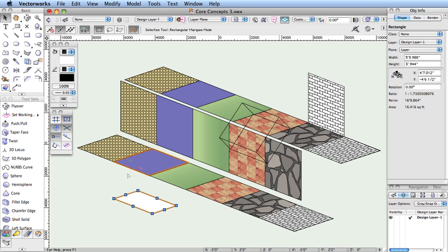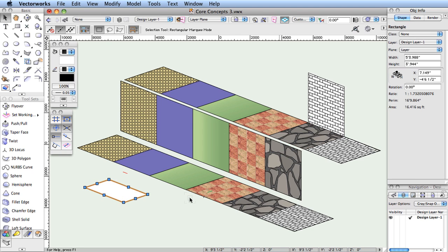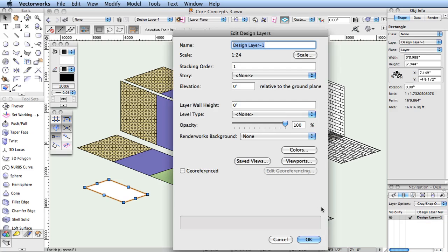The ground plane is a fixed horizontal plane with its origin at the center of the drawing space and at the level of the printed paper. Ultimately, the ground plane is the first consideration for how the location of any point is listed. There are several functions that can affect this behavior, however. Objects and layers with an offset to the ground plane report their height relative to their layer plane, whether or not the layer plane is offset from the ground plane. So, when not defined by you, the working plane defaults to the active layer plane, which may be 0 when the working plane is called the ground plane.